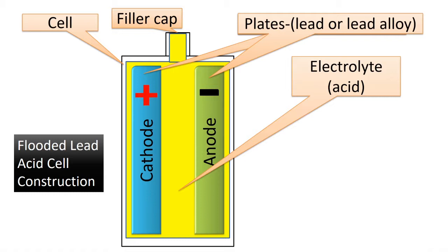Early in the history of battery development, battery designers were faced with a design challenge. They found that lead was the best material electrically, but is a soft metal that's easily bent. The designers found that by making the plates thicker and combining the lead with other materials, typically antimony for deep cycle applications, they were able to prevent plates from bending while being suspended in a liquid electrolyte.